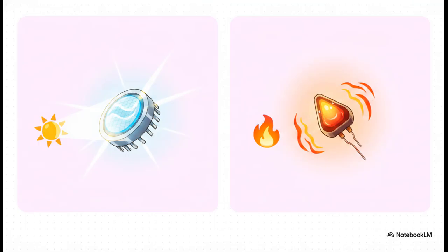All right, let's check your intel. Circuit A uses an LDR, which is a light-dependent resistor. A fun way to remember it is Larry LDR. More light equals less resistance. Circuit B, on the other hand, uses an NTC thermistor. That's a heat sensor where the resistance drops when things get hot. So one detects an intruder flipping on a light, and the other detects a fire. Make absolutely sure you use these exact terms in your worksheet for your Grade 9 technology exams.